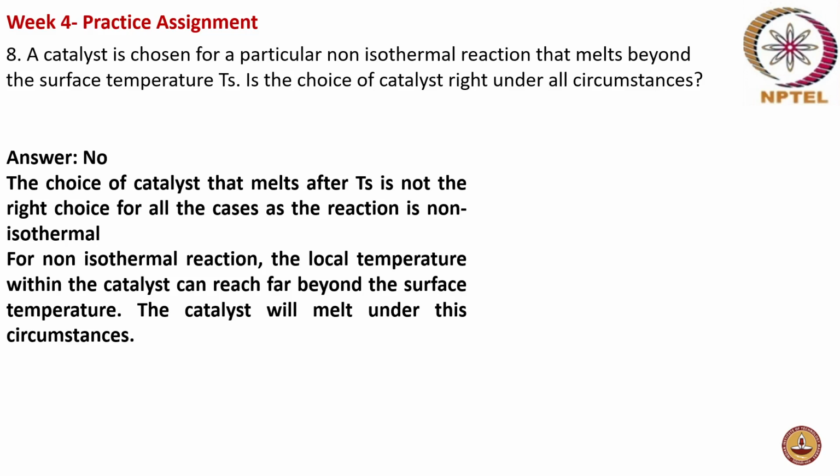Since it is a non-isothermal reaction, it might increase within the catalyst. That means the catalyst will start melting and there will be loss of catalyst. If the temperature shoots up beyond Ts, it will start melting and you will lose the catalyst, and your total process is stopped with the loss of catalyst as well.